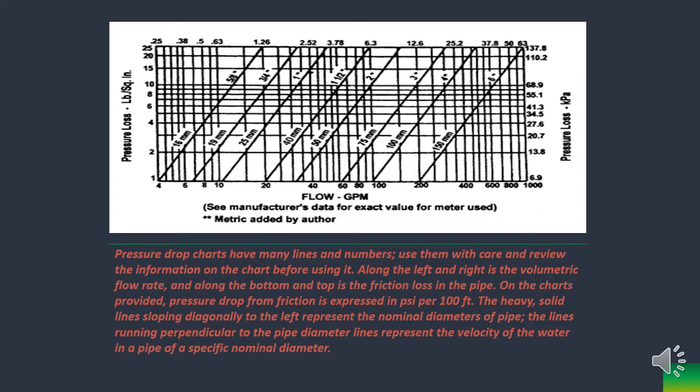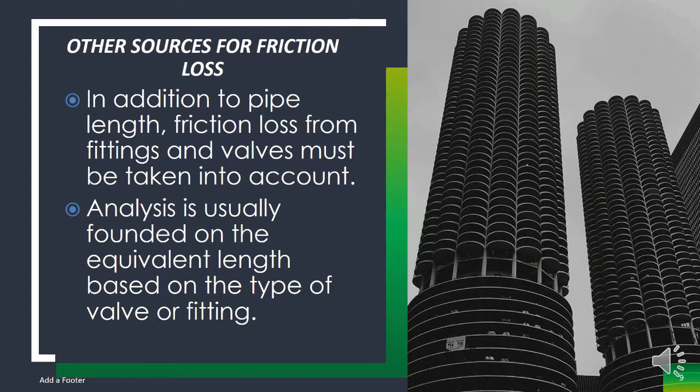Other sources of friction loss, in addition to pipe length: friction loss from fittings and valves must be taken into account. Analysis is usually founded on the equivalent length based on the type of valve or fitting.